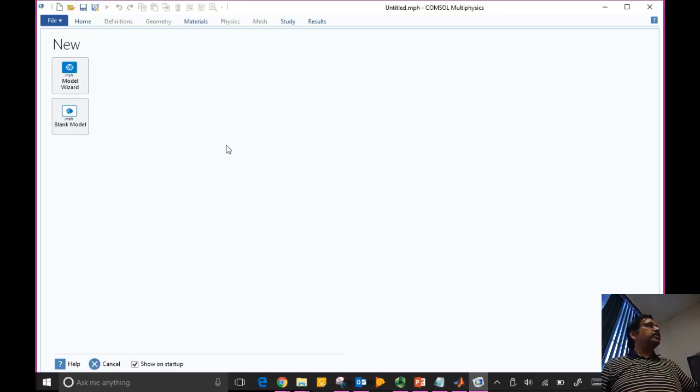And in COMSOL, there is a link to MATLAB, so you can actually write MATLAB functions and feed them into COMSOL. But for that, you need to start in a slightly more complicated fashion called the server-client fashion. So you will start a MATLAB server, and it will talk to COMSOL. Okay? But this is the simplest COMSOL starting. So just pick the Multiphysics icon and click on that.